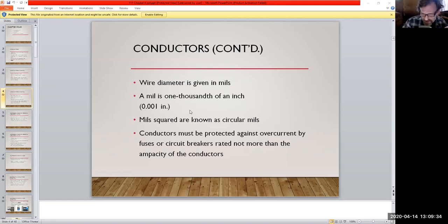It's actually used in formulas in conjunction with the kind of wire, like if you're using copper or aluminum, you would actually multiply that in there as well, because copper and aluminum are not the same animal. And we'll show you later with a formula. They call it K for constant. K for copper would be one number, and then K for aluminum would be an entirely different number.